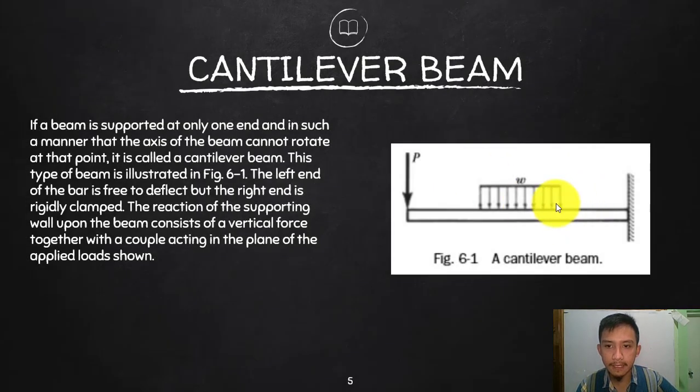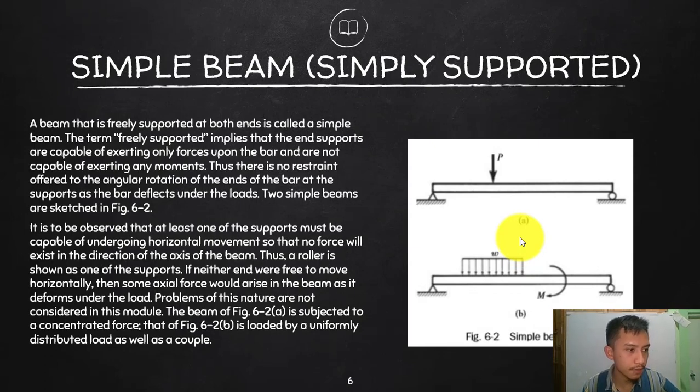In this analysis, we will first try to limit ourselves to determinate beams. We already discussed what is determinate, wherein the reactions or the analysis of the entire system can be done by plain statics of equilibrium. So we will focus first on systems wherein we can solve the reactions by means of the static equilibrium equations. So with simple supports on both ends, there will be no moments.